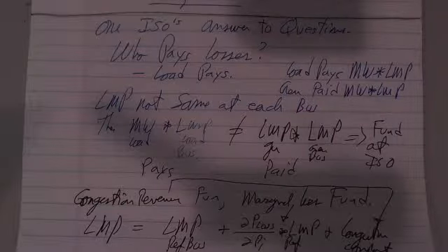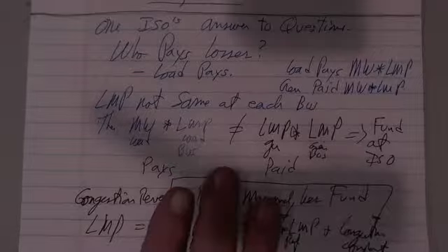The LMP components are calculated: an energy component, that's this guy, a marginal loss component, and a congestion component. The LMP components are only used for settlement purposes. Settlement is when we come back and say, okay, who gets what? Who gets money paid to them? Who has to pay? That's called settlement. So it's like at the end of the day, there's a settlement process. Essentially, at the end of the month, they're going to have to get the books straightened out.